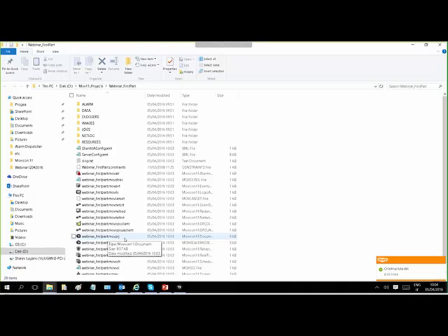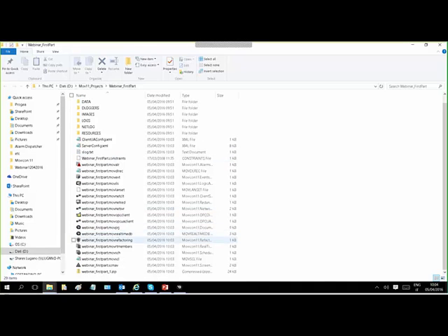It is the file that you use together with the Movicon Runtime X to directly start the runtime of your project without passing through the development environment. All these files are related to a different project resource. We have a file for the real-time database, the variables. We have a file for the alarms, and so on. Here is how our project is organized.